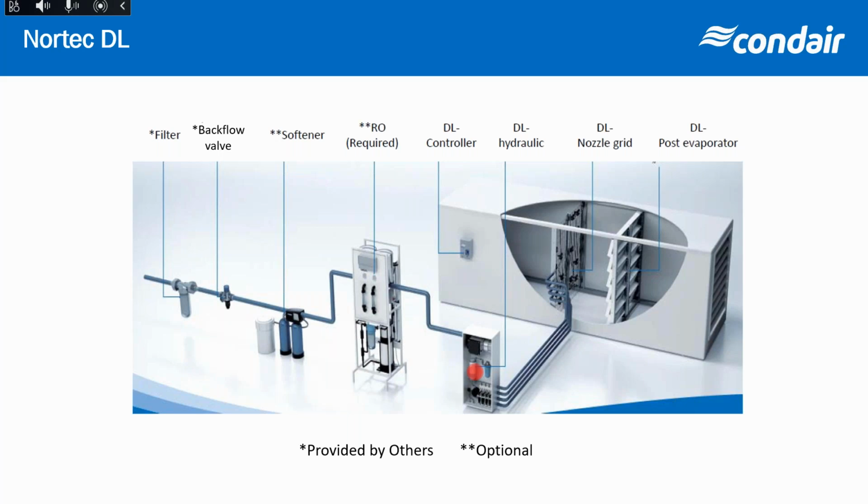The other thing is that, unlike a lot of RO people that operate RO, where the tendency is to make hundreds and hundreds or thousands of gallons of RO water and store it in a clear tank open to atmosphere as required by code, our tank is very small. It's black, so it can't be affected by sunlight. And our opening is a 0.2 micron HEPA filter.